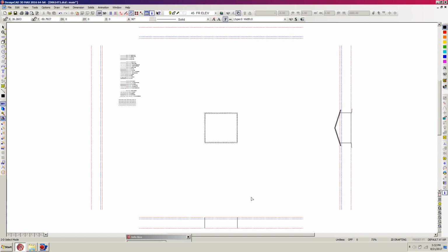So what do we do about the roof? Well, here's the easy thing to do to deal with the roof on the front elevation. And this is part of the beauty of actually folding things out from the floor plans. I'm going to select our right elevation here, and I'm going to set a handle somewhere on this floor line. So I'm going down here to set selection handles. I'm clicking on it. And I'm getting near this line on this lower portion, and I'm going to just hit K and then hit Enter. So now it's set a handle on that floor line.